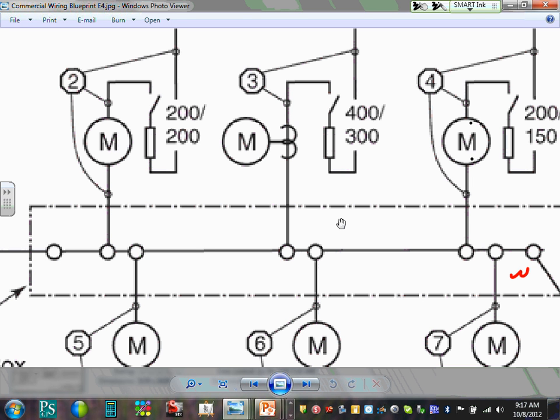These are meters with CTs. Up to 200 amp, guys. You can buy a meter that can handle 200 amp, and even 300 amp, I think some of them are 300 here. If you go 400 and higher, you can't bring the 400 amp directly through the meter.